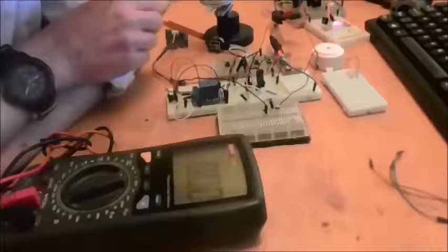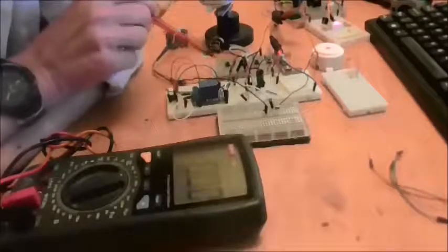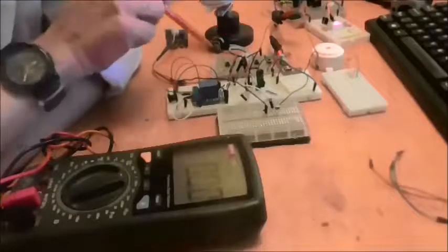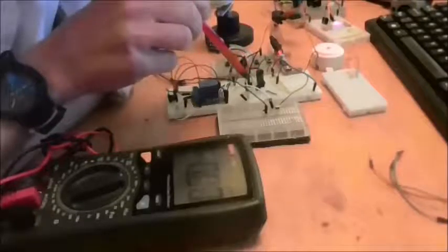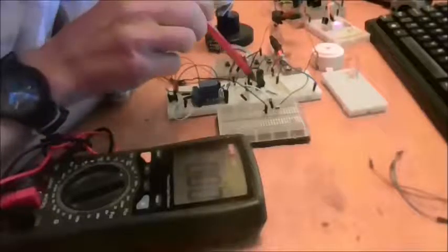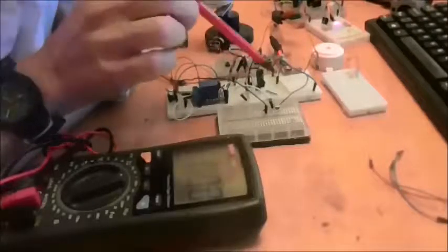We've got input number 1, the PIR sensor, and we'll shut the window so we don't set it off accidentally. Input number 2, the reed switch and magnet. Input number 3, the pressure mat, or the simulator thereof, which is actually 4 buttons. All going to a 3-input AND gate made out of these transistors. The 3-input AND gate is outputting to a relay, and whatever position the relay's in is outputting to this transistor, which switches the alarm on or off.